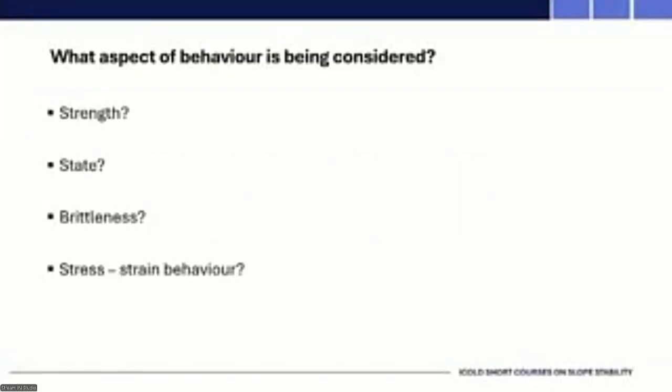All right, so a couple of thoughts on undisturbed sampling and testing to pick up from what SW was saying. I think one of the things to ask yourself is, what am I actually trying to measure? Too often, I think we do something because it was done before. What aspect of the soil behavior are you really interested in? Is it the state parameter? And in fact, do you want to just know that you're in the contractive region, or you're safely in the dilative region?